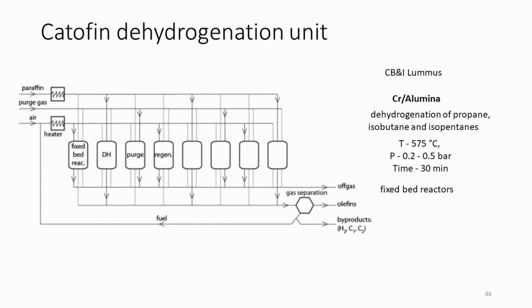Part of the heat required for the reaction is introduced to the reactors by preheating the reaction feed, with additional heat being provided by adjacent reactors that are regenerating the cold catalyst. Moreover, fuel gas is added to the reactor during the regeneration step to generate supplementary heat, and inert material is added to the catalyst bed to increase its heat storage capacity.